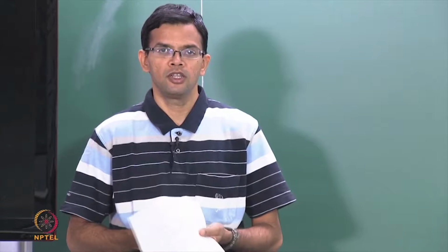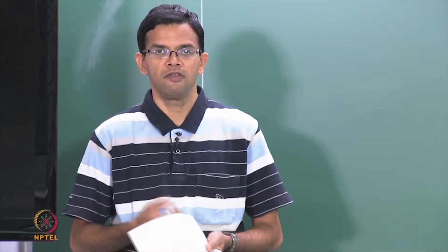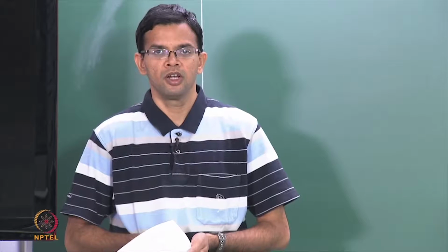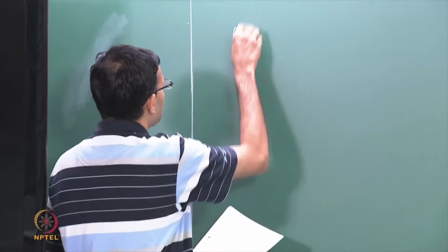by dry etching. We also looked at the opposite of the etching process, which is the growth process, where we add material to the wafer. We mainly focused on growth by a chemical vapor deposition process. Today we are going to continue to look at growth processes. We are going to look at formation of metal layers. This process is called metallization.